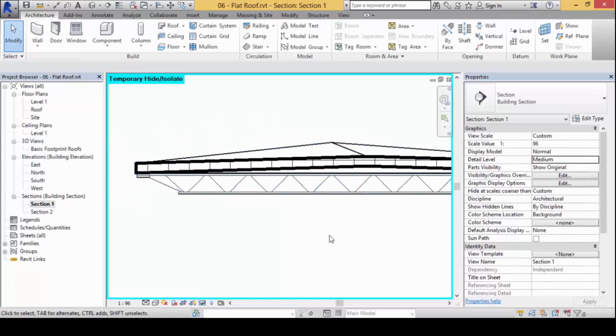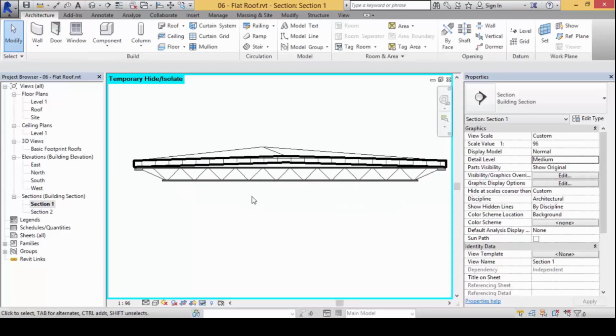That was the error message. It doesn't accurately reflect thickness and so on. In reality, when we really construct this, we don't construct it like that. We construct this lower portion here as flat. And then we build materials up here in order to create that difference in levels for water to flow. We either add more material, more cement, more concrete, and then things will flow down accordingly.